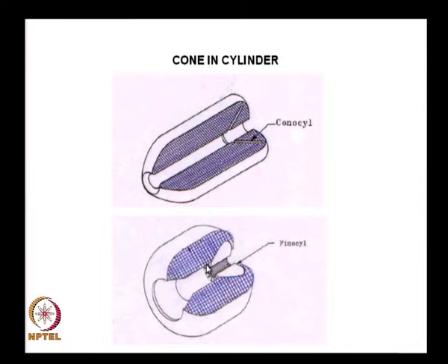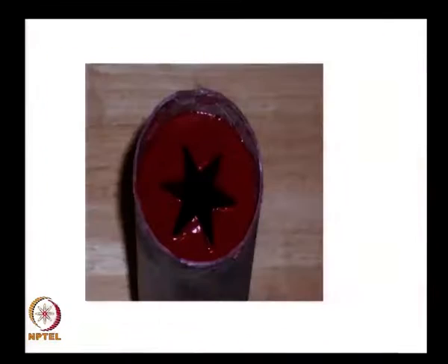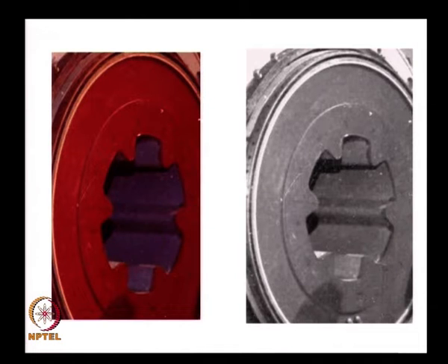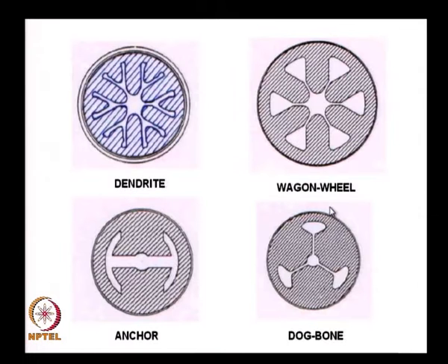Therefore, there are various grain shapes, but what is maximally used amongst this is something like a star grain, which is used quite intensively. We will see the reason in this class. We also find such shapes are used quite extensively, and these are a little rare, though the wagon wheel tends to be used in some specialized cases. Therefore, we could have anything.